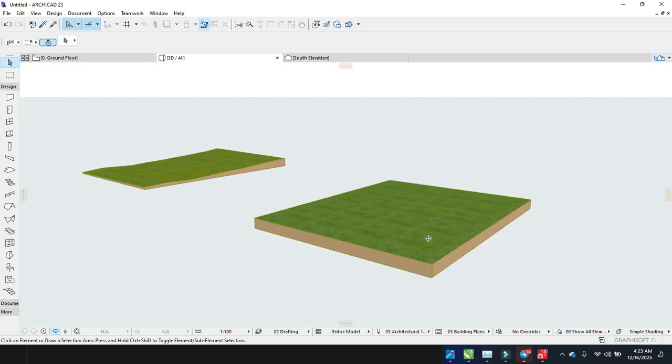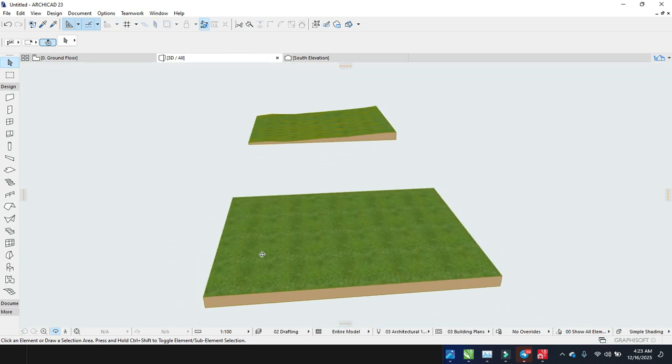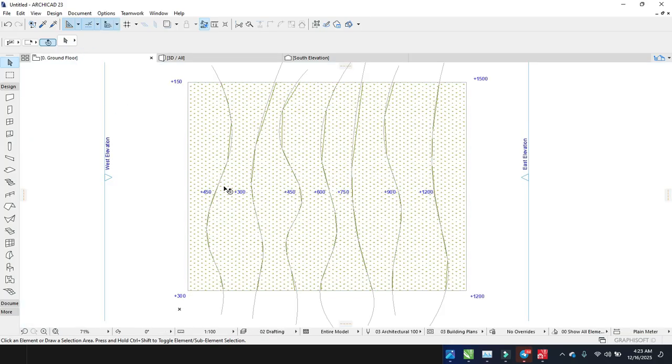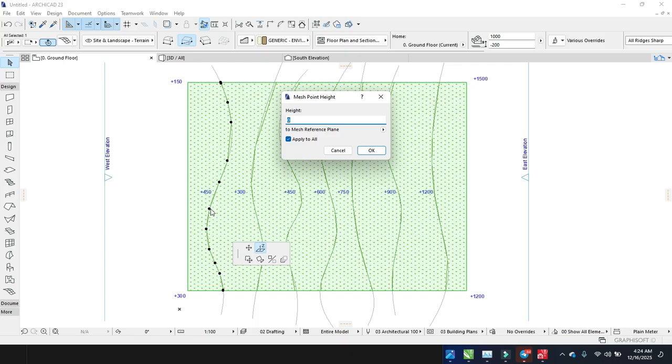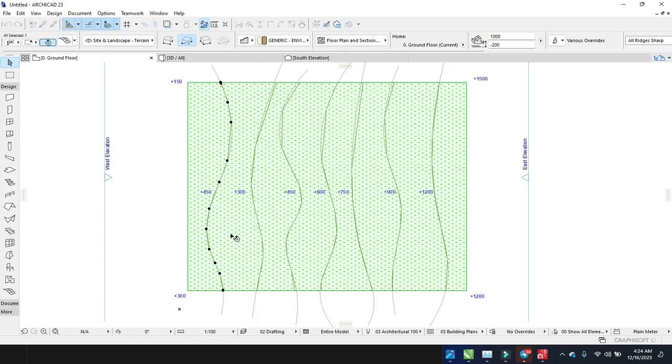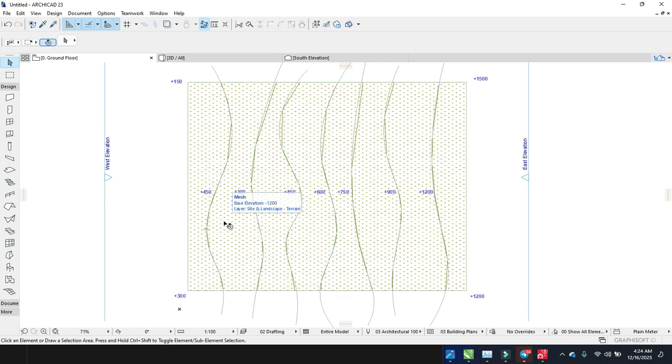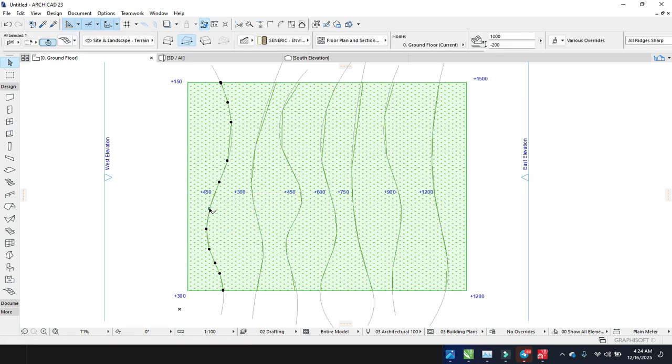Nothing has changed here. They are still the same height, because we've not specified heights for the different splines. So select your mesh again, and click on any point along the line of the splines. Sorry, hold on. When you select your spline, you click on any point there, then click on it again. Now this option comes up, so you should not get confused.